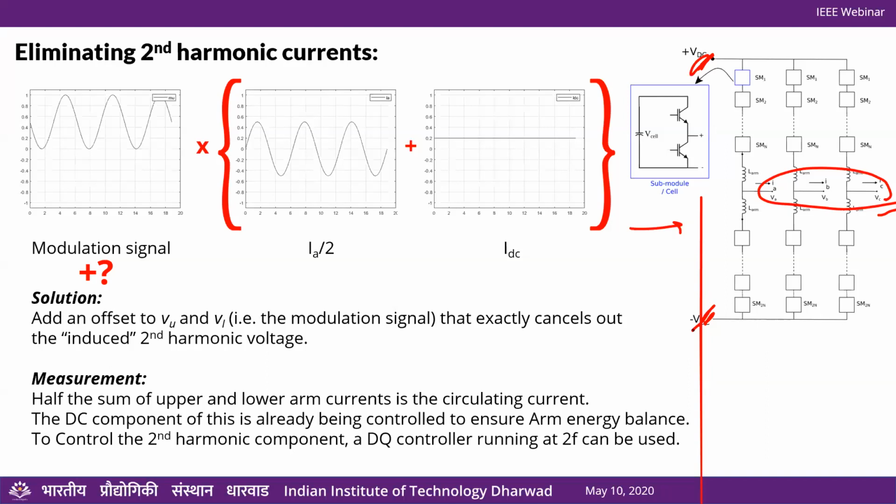I think the latest standards only permit up to 1.5 kV DC link voltages for PV strings, right? So you would need some sort of a solid state transformer or some sort of a DC-DC converter to bring it up again to this high voltage. And I'm not sure if in the case of PV, where maybe utility scale, you have loads of land, there's not really so much constraint in terms of size and weight. So it may not be the best way to connect PVs using this arrangement.